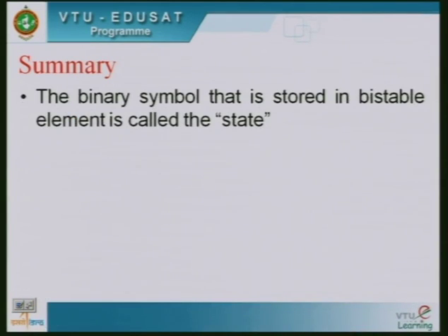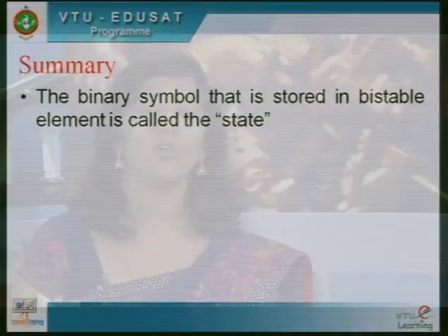So, in summary, what is a bistable element? A bistable element will always have storage of a binary symbol in a form known as state. So, it stores a binary symbol known as state, and it normally has two stable states. One is when Q is high and Q bar is low, the other one is when Q is low and Q bar is high. So, generally we depend on Q. Q is the value stored.